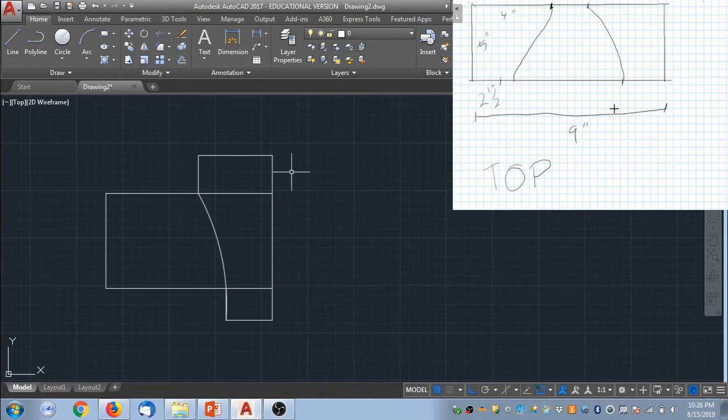Although it is a little long, so in order to get it to fit the constraints of the rectangle, I'm going to cut away my construction lines. And then I'm going to use the trimming tool right here and use the edge of the box to trim away the excess arc and delete the construction line under there.